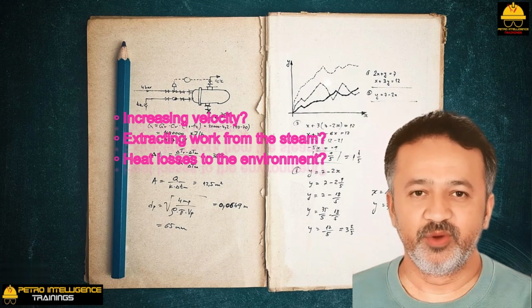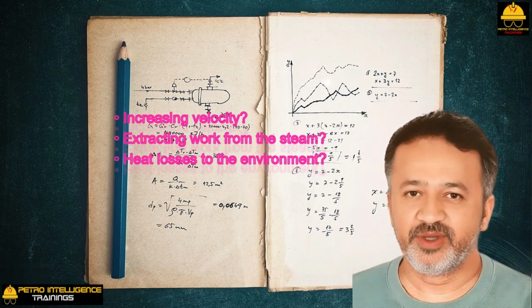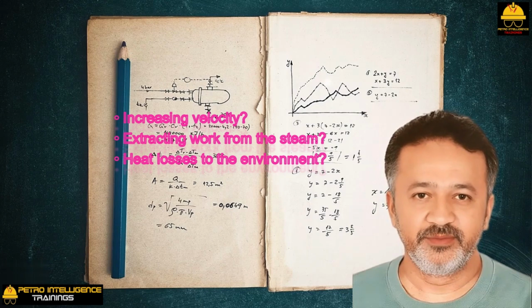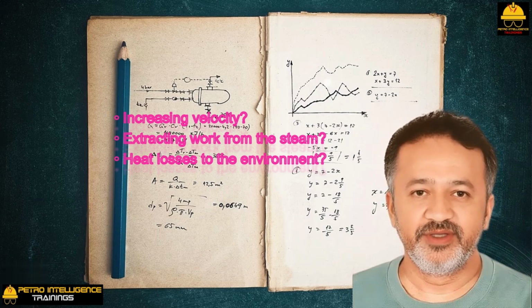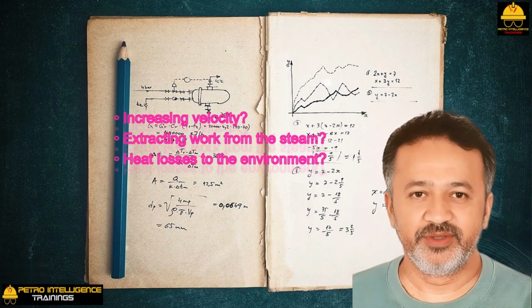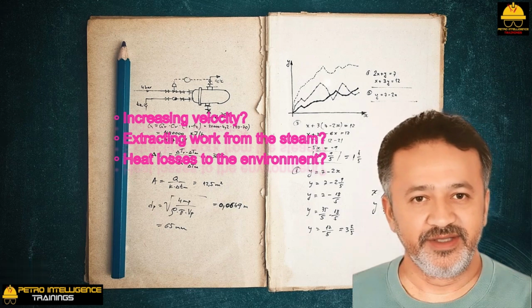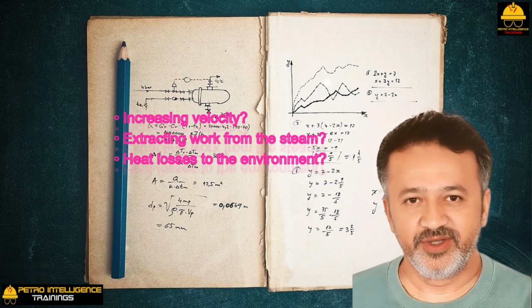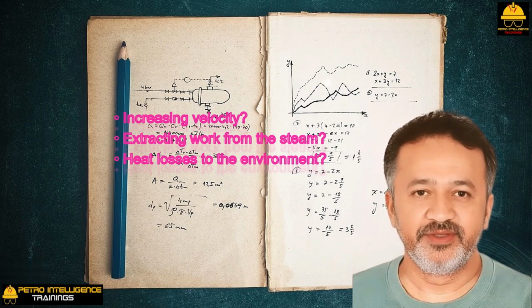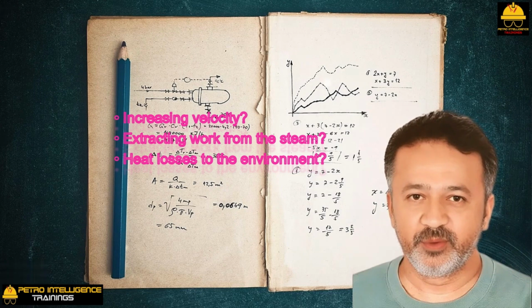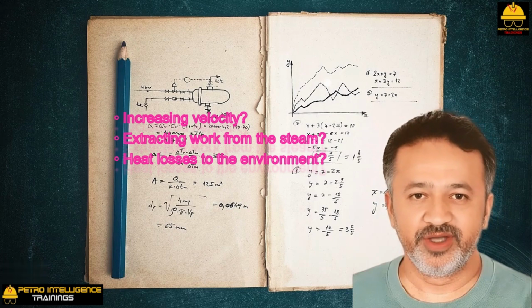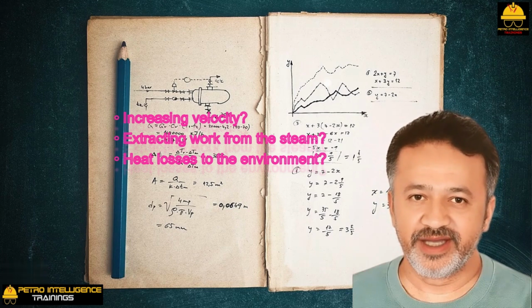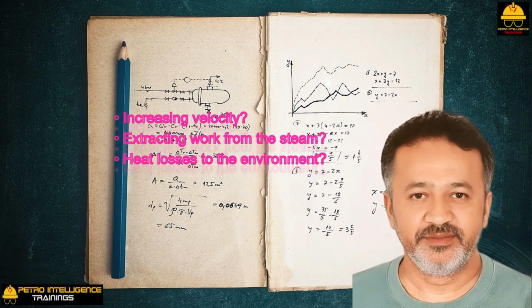The answer is that at a lower pressure the steam molecules move away from each other, which then lowers the frequency of molecules colliding with the temperature sensor. However, as the molecules move away from each other, the latent heat of condensation stored up by the molecules increases. In effect, just lowering the pressure without any change in velocity converts some of the sensible heat of the steam to latent heat of the steam, but without any effect on the heat content of the steam. This is also true for light hydrocarbons, ethane, propane, butane, but not for hydrogen.